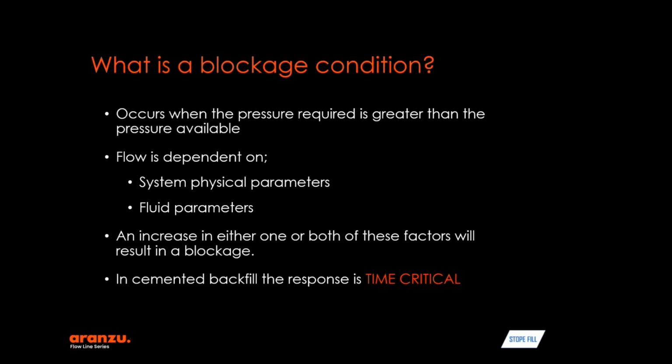Maintaining flow is also dependent on fluid rheological parameters such as yield shear stress, fluid consistency index, and the flow behaviour index. An increase in either one or several of these factors will cause the flow to stall or become a local restriction, stopping flow and resulting in a blockage condition. In cemented backfill, the response time is critical.